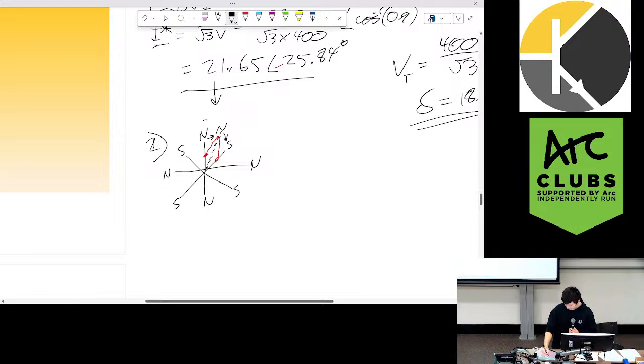In terms of electrical angles, this is 90 degrees. Mechanically, you divide that by the number of poles on 2, so the number of pole pairs, in this case 4. So that would be like 22.5 degrees. So that is that. So 90 degrees electrically.